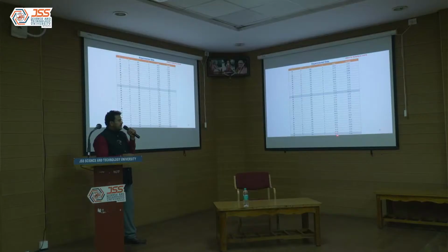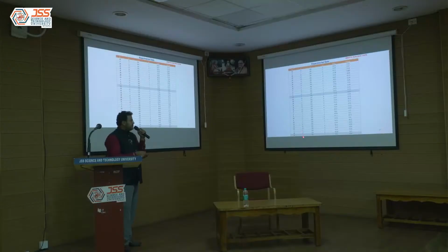observed in the last experiment, that is the last run, when the applied frequency is 15 kilohertz and the extrusion pressure is 7 bar, and when we use 300 mesh size and 7 minutes of processing time, we observed better delta RA, means better surface finish.